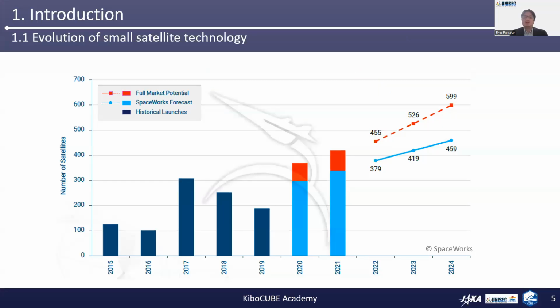Over the past 20 years or so, we have seen a growing trend toward the launch of small satellites weighing less than several hundred kilograms, rather than the conventional satellites weighing more than 1 ton. There are various categories of small satellite weights. Satellites weighing several hundred kilograms are called small satellites in the narrow sense of the term. Microsatellites weigh from 10 to 100 kilograms, and even smaller satellites are called nanosatellites or picosatellites.